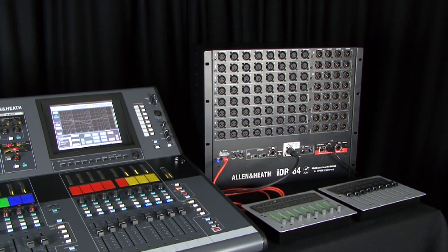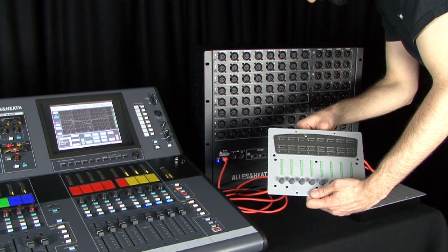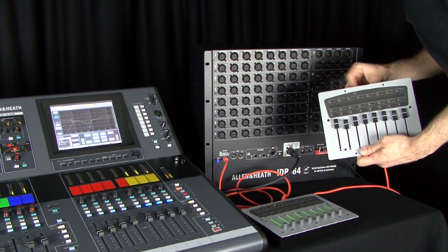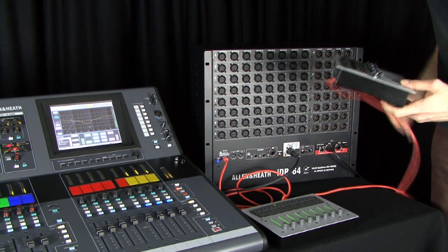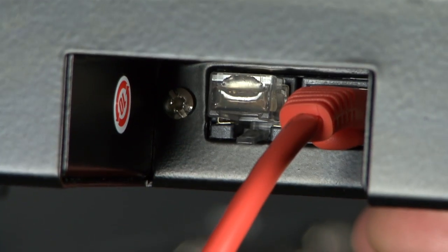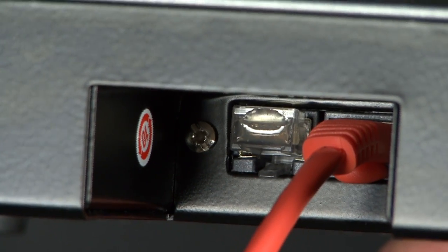PL devices must be connected before assigning their controls. Several remotes may be connected by daisy chaining Cat5 cables between them. Make sure that the last device in the chain has its end-of-line terminator plugged into its output socket. Check that all connected devices have their green power LEDs illuminated. If the LED is off or red, then check the cables and connections.